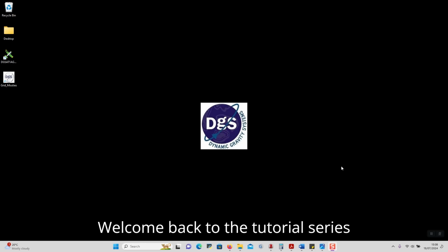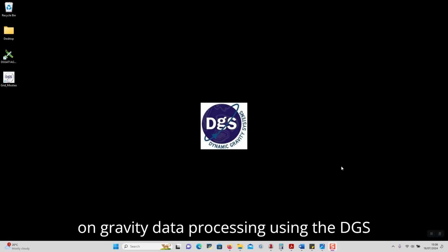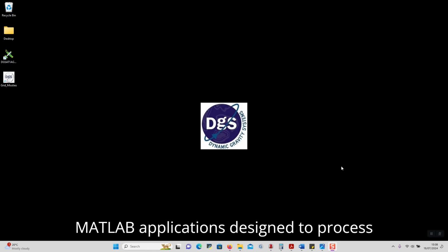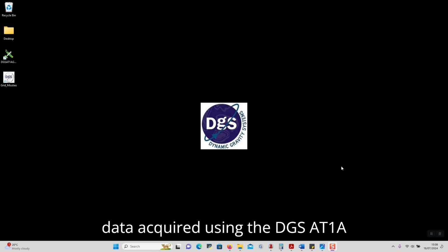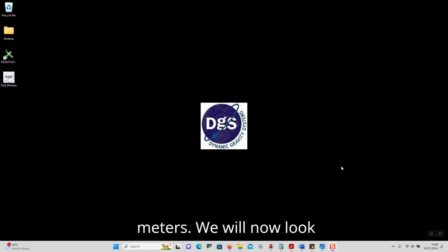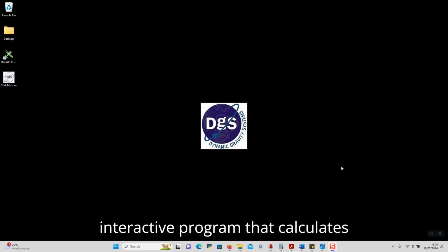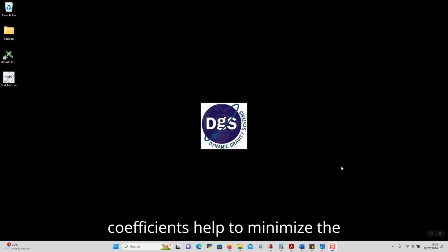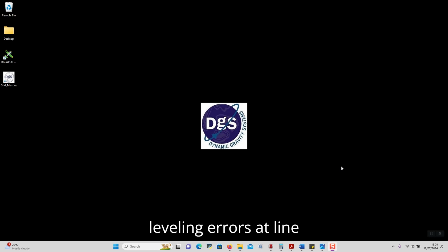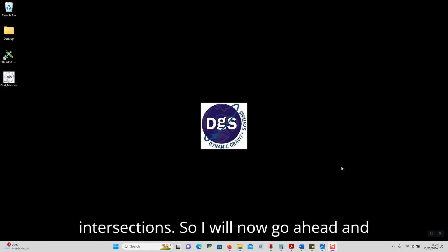Welcome back to the tutorial series on gravity data processing using the DGS MATLAB applications designed to process data acquired using the DGS81A meters. We will now look into the line crossings tool, which is an interactive program that calculates cross-coupling coefficients. These coefficients help to minimize the leveling errors at line intersections.